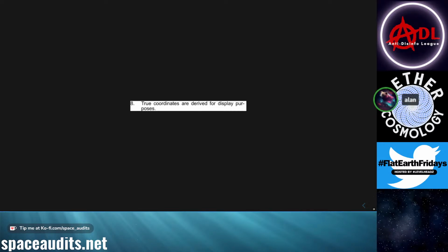So we have number 8 now. True coordinates are derived for display purposes. So after all that computation on the back end, the last piece of algorithmic aid that's given to us by Kalman is we get to see our location on the true coordinate system. So it gives your location on your reference ellipsoid of your choosing. Your favorite ellipsoid, spheroid model, whichever one you want to choose, you can align it to that. Yep.